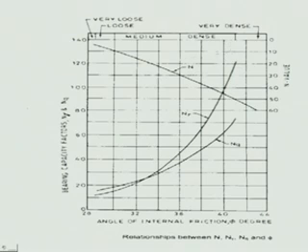So, either we take the phi value from here and then the Nc, Nq, N gamma parameters can be determined from the Terzaghi table, or directly from this chart, in which the intermediate values are covered from the local shear failure case to the general shear failure case. This is the chart given by Peck et al. So, here for the given value of N, we can directly find out what is the value of N gamma and what is the value of Nq.